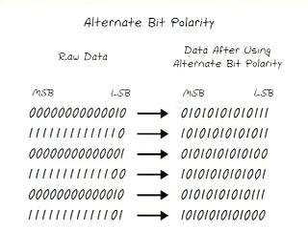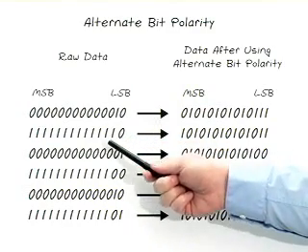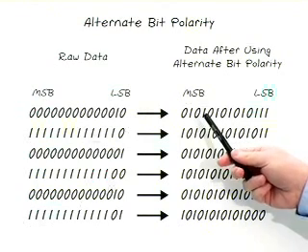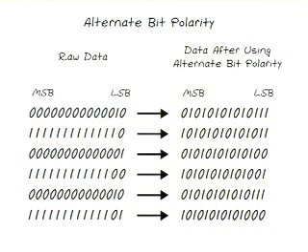In this example, we have a signal that is exercising a few codes around mid-scale. On each sample, all of the high-order bits are swinging from 0 to 1, which generates large ground currents that can couple back into the analog input, maximizing digital feedback. When alternate bit polarity mode is used, every odd data line is inverted. This means that instead of 14 data lines switching between 0 and 1 together, half are switching in one direction and half are switching in the other direction. This provides a cancellation of ground currents to provide a significant reduction in digital feedback effects. To decode this data, a simple inverter would be needed to implement in the receiver on each odd data line.